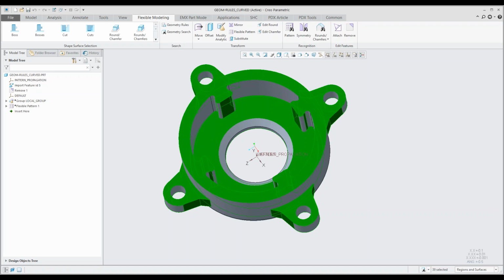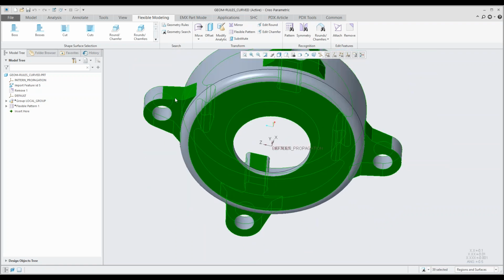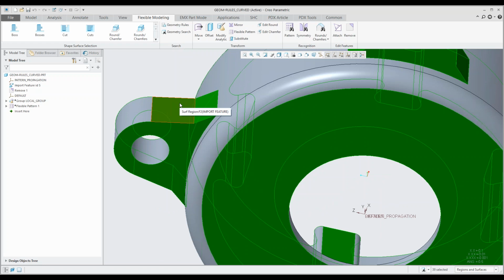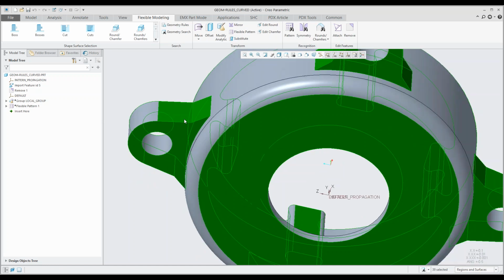So there's a few warning signs from a CNC guy here. So I've got a few surfaces. Let me just rotate the part a little bit and highlight that. So you'll see that particular surface, I'll need some special machining method that I'll need to apply there. Maybe I've got a 5-axis machine or just a 3-axis machine. That will determine how I machine that particular surface. But this is just a nice way of selecting surfaces, and you can use it to verify certain surfaces.